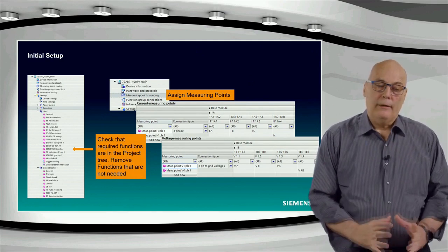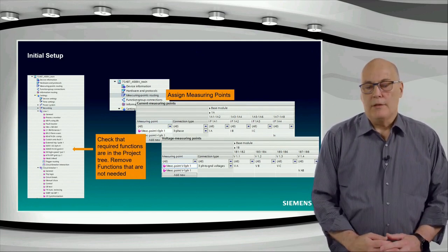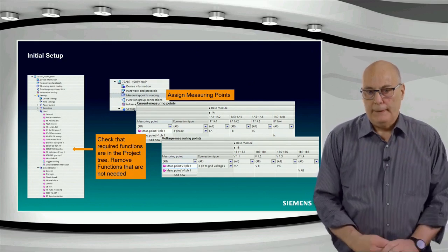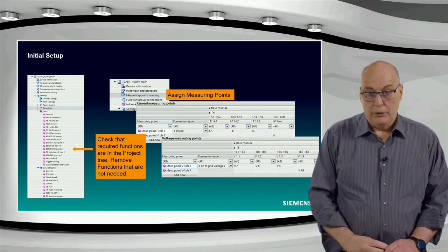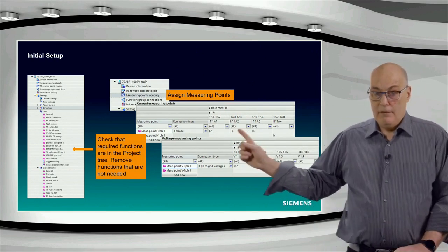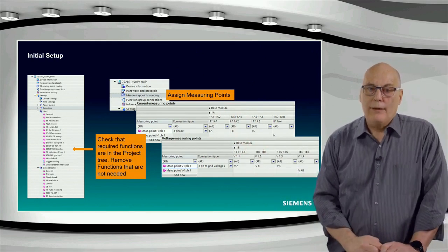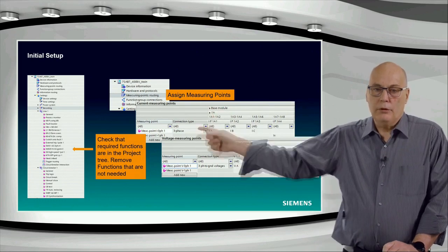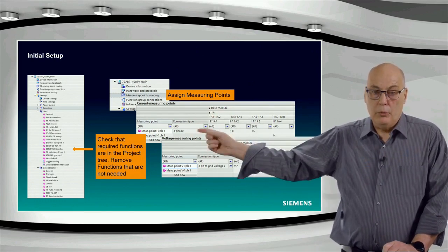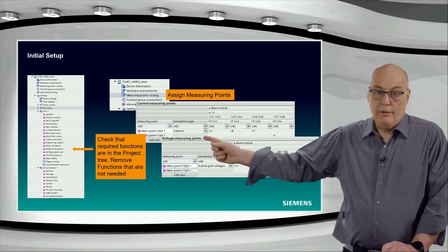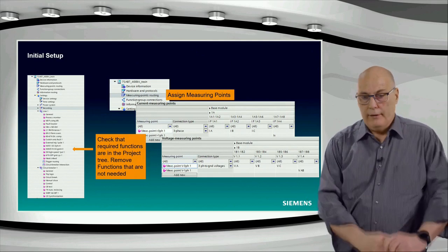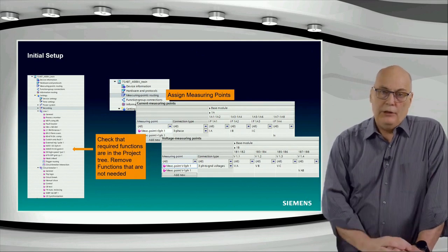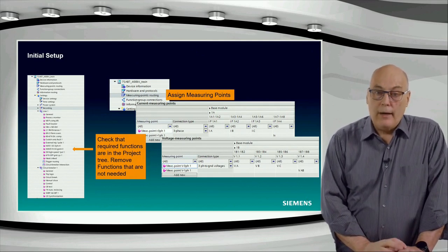If you're going to apply that, you have to make sure that the CT and VT is connected to the function. That is done in the DIGSI configuration under the measuring point routing. And you can see here, physically in the middle, that would be the current measuring point. So I have defined here two current measuring points. It's interesting, the one, a 3-phase current measuring point, is going to be the one connected to the protected line. And as mentioned at the beginning, we want to look at parallel line compensation.